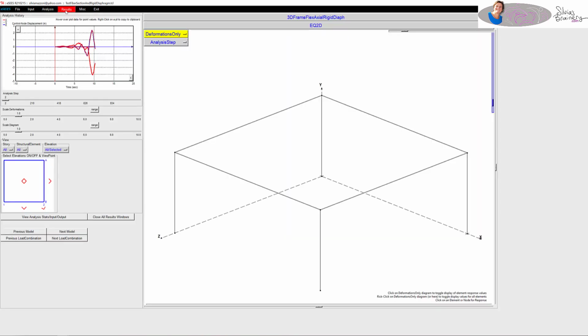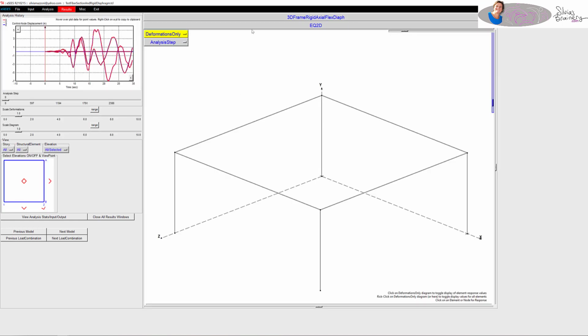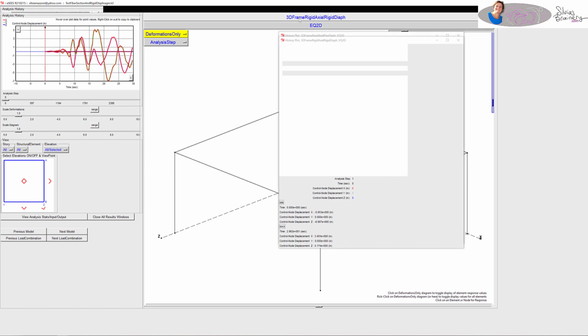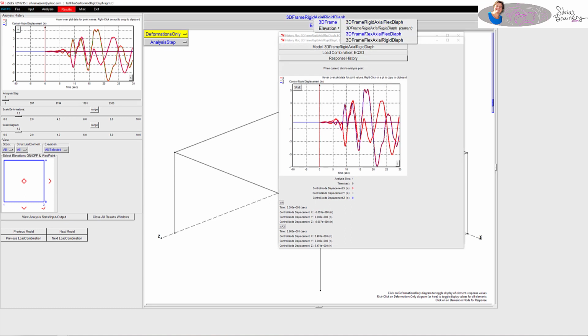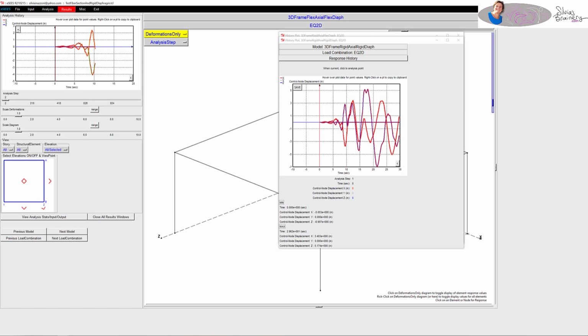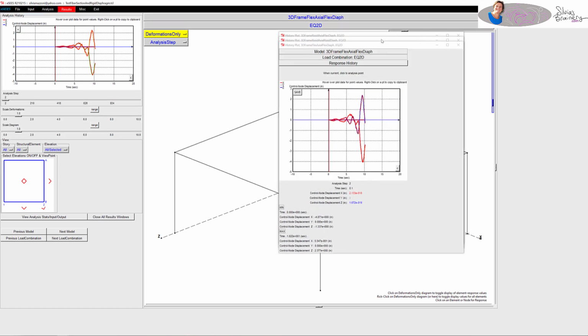So now I'm going to go in and collect similar data as I had done before. Now what we're going to find out is whether you have a rigid diaphragm or not, you get the same results. That's because we have a symmetric section, the masses are evenly distributed, so there are no eccentricities. And so I don't really see a rigid diaphragm making a difference. But it's just here to make sure that I have all 4 cases. If we had some more 2D effects, then I would see a lot more.